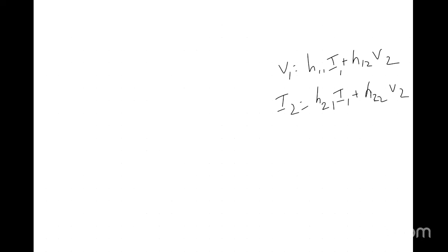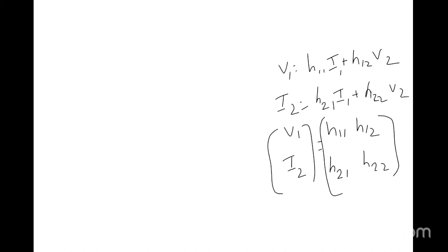Now, using this, I am separating the voltage and current variables from the H parameters. Across the LHS terms I am writing V1 and I2. Together with these, the hybrid parameters I am collecting as H11, H12, H21, and H22. These are the hybrid parameters. And on the other side, the variables, while I took V1 and I2 on the LHS, here I will take I1 current and V2.